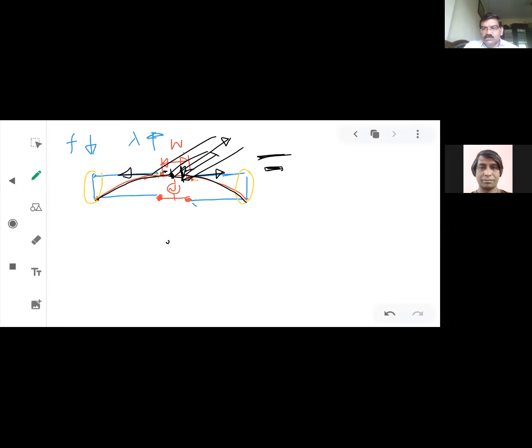You will reach a situation where the wavelength has increased to such an extent that the standing wave formed in this three transmission line system has its minima at the same place, because a short circuit is occurring on the left hand side and the right hand side.